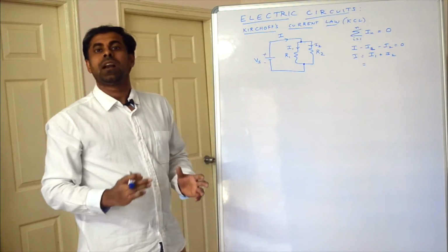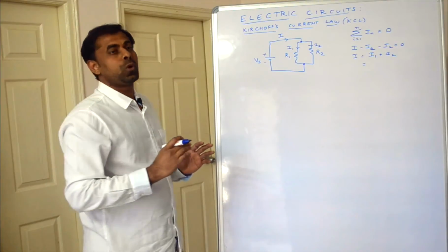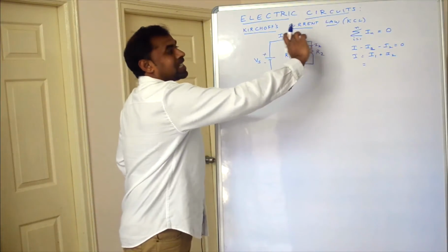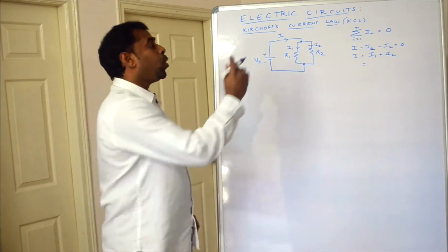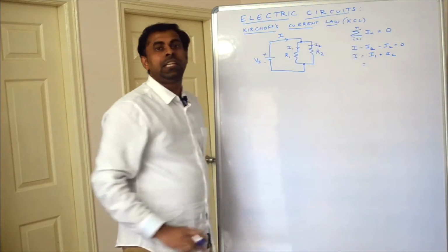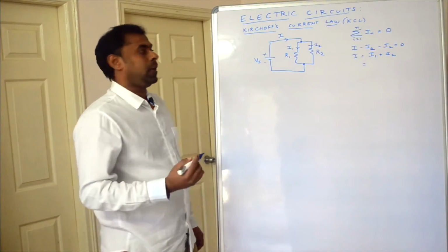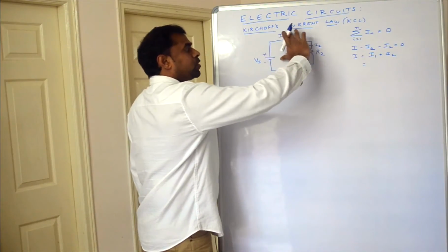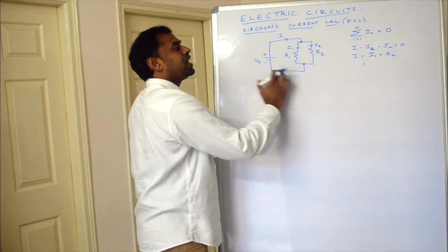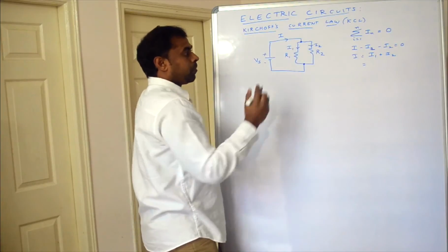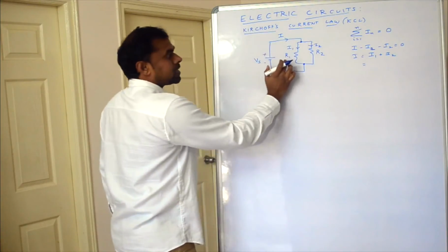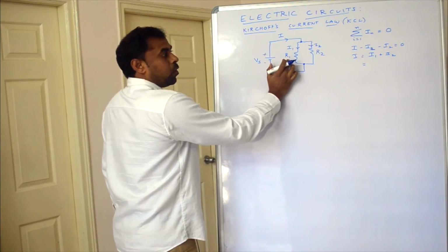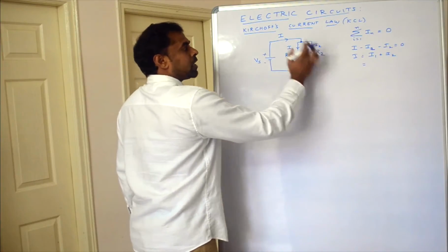These two elements are having two junctions as common and no other element is connected there. Then these two are said to be connected in parallel. Here if you see, same voltage source is applied across each and every resistance. Okay. So that means voltage across R1 is Vs, voltage across R2 is Vs.